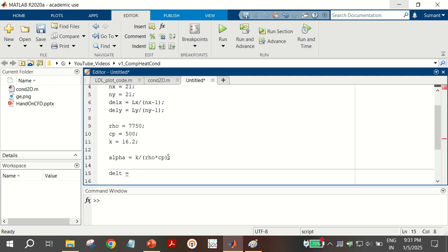If you take a too long time step, a very high time step, you will miss the information being transmitted from the left plate to the right plate. Say, for example, the heat is moving from left to right plate, and in 1 second it can only move 0.1 meter, and you take a grid length of 0.1 meter, but you take a delta t of 2 seconds.